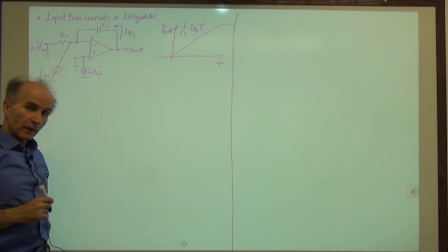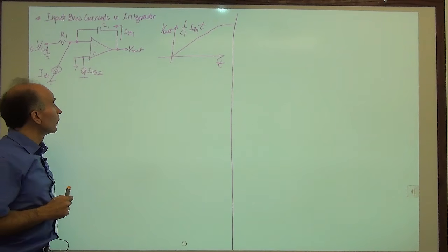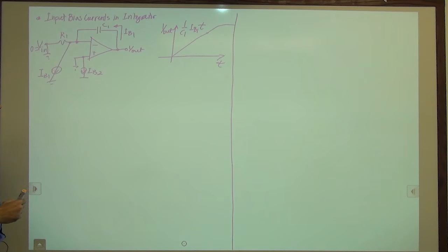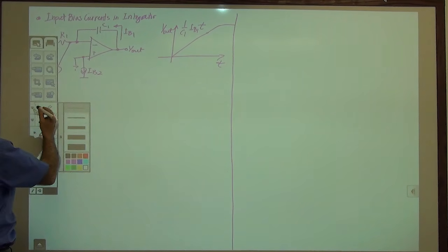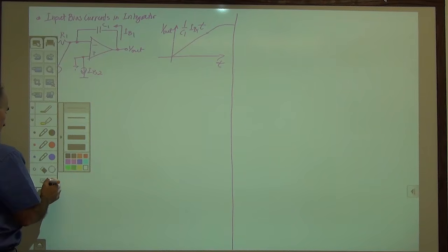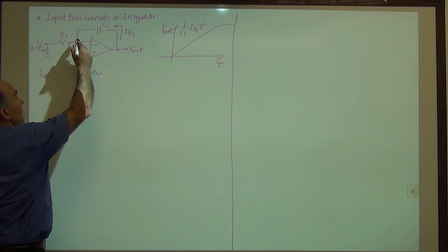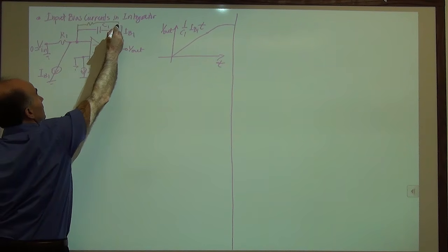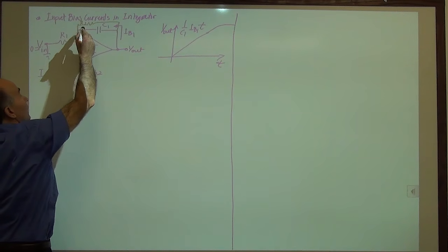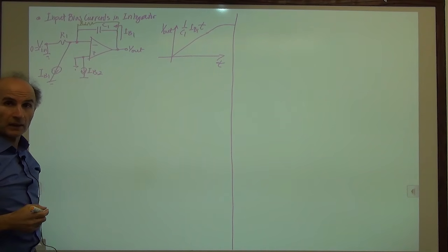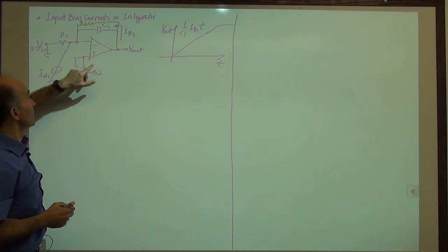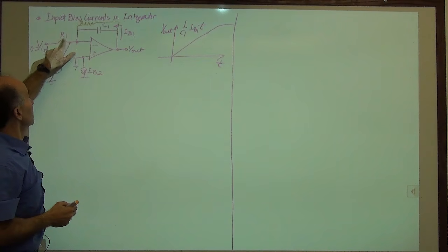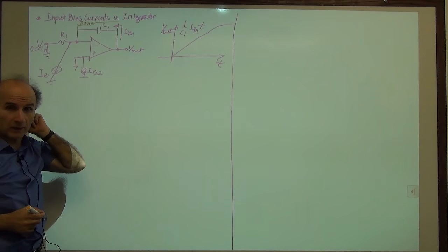Okay, so how do we alleviate this situation? Well, a partial remedy is this. A partial remedy is to add that resistor there. That resistor looks like this. Remember that resistor that we put here? That's really the only reliable solution that ensures that the circuit does not saturate. It forces any currents that we need to draw from here to flow from R2, not from C1.